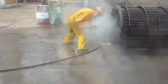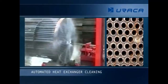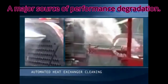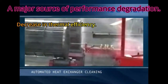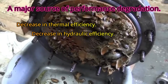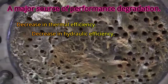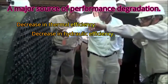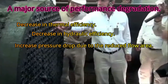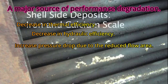Fouling of heat exchangers. Fouling in heat exchangers represents a major source of performance degradation. Fouling not only contributes to a decrease in thermal efficiency, but also hydraulic efficiency. The buildup of scale or other deposit increases the overall thermal resistance of the heat exchanger core, which directly reduces the overall thermal efficiency. If buildup of a fouling deposit is significant, it can also increase pressure drop, due to the reduced flow area in the heat exchanger core. The two effects combined can lead to serious performance degradation.